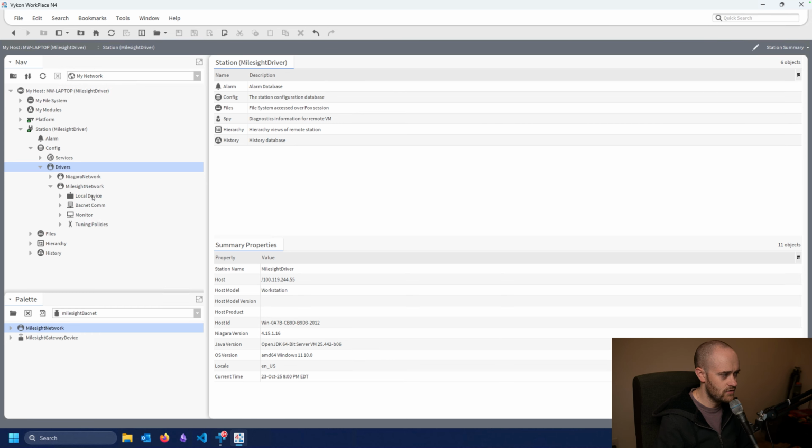So we will now go back to our subdevices folder, and you'll notice at the bottom here, we actually have all of the functionality to do our bulk import of a bunch of devices directly from Niagara. It even gives us access to that template that will fill out with all of the details on our individual devices, and then bring that template in through the bulk import.